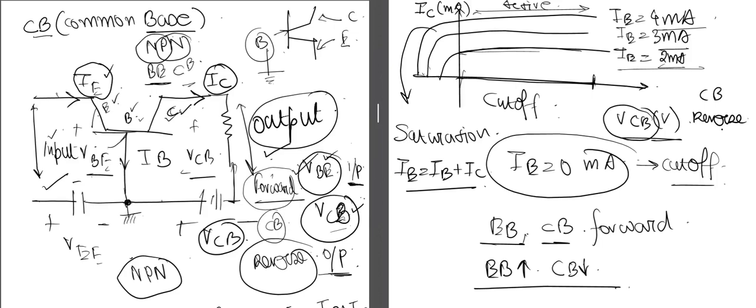If we reverse bias the collector base junction, the depletion region between the collector and the base terminal increases. So the electrons can't pass through from the base to the collector terminal. At a particular value of VCB, the current no longer increases, because no more electrons can pass from the base terminal to the collector terminal. So the collector current IC has become constant.